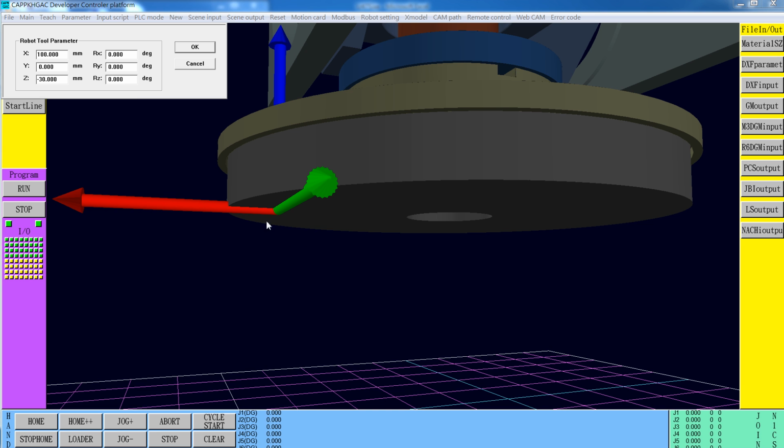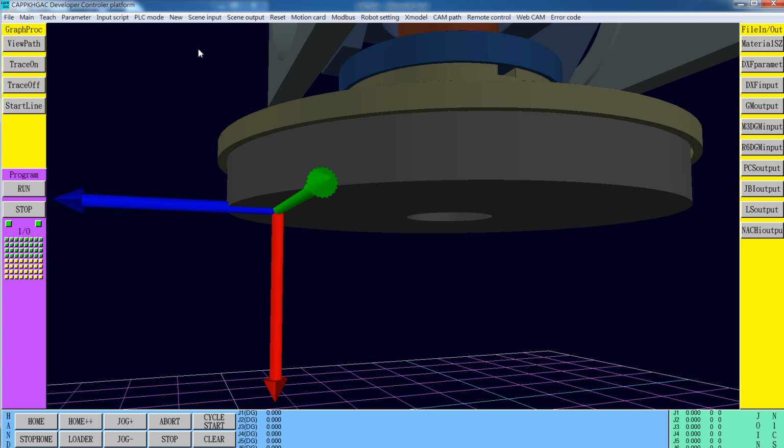It is like this point. If we rotate about the y-axis 90, the TCP becomes this shape. After grinding this point, because it is turning in a circle, all around the circle is removed. If we need a new point for grinding, we can set the TCP point to another point.